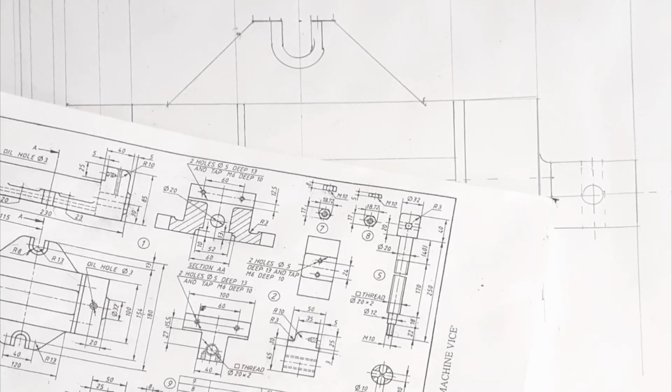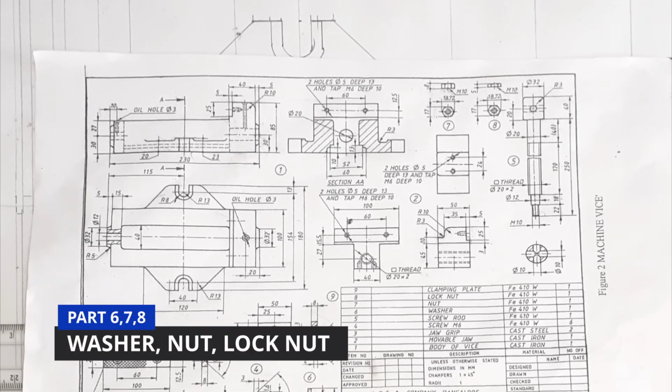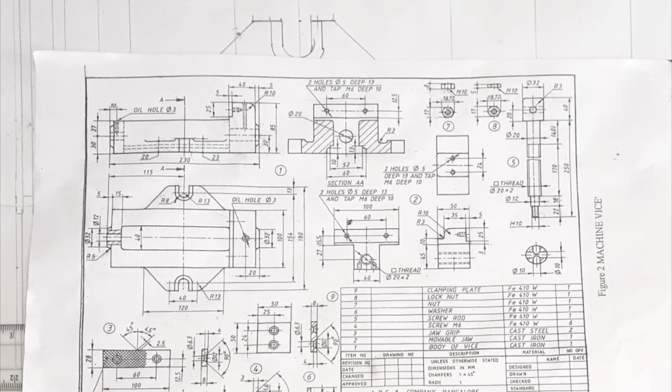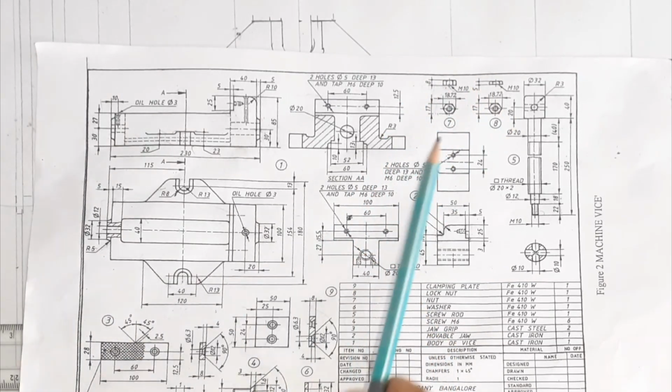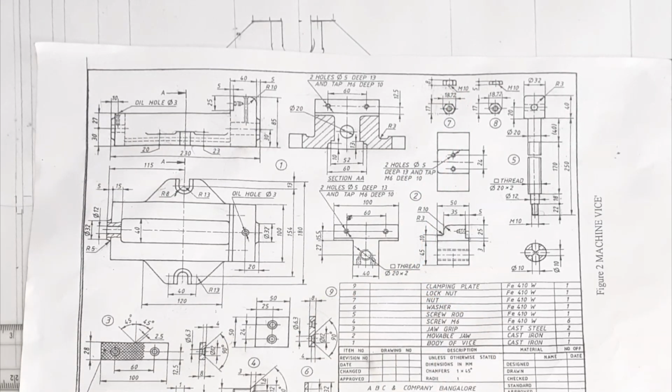Next is part number 6, 7 and 8. So part number 6 is washer. It has the width of 3 mm. So we will get it from the front view and draw this one. Next is part number 7 and 8. So here this also we have to draw similar to what we have drawn in the front view, that is we have to mark the widths of 8 mm and 5 mm, and this will have the diameter of M10, that is for the hexagonal nut it will be 2 into D, that is 2 into 10, 20 mm. So it will be having the diameter of 20 mm and the length of 8 and 5 mm respectively. So let's draw these parts.